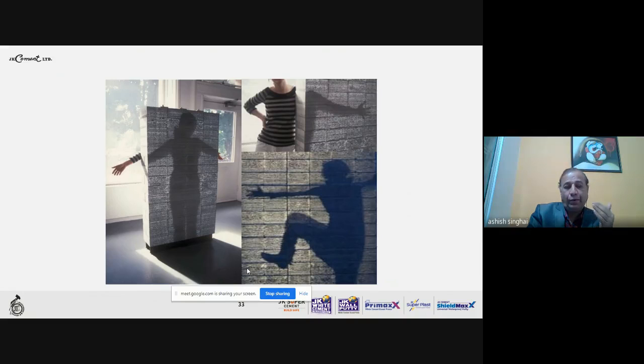So it has a good amount of water resistance. As I mentioned, the overall strength is 50 megapascal, and it has a good density because of the 90 to 95% finer materials. Coarse aggregates are almost negligible. About 4% is optical fibers, 90 to 95% is fine aggregate, and some binders and other chemicals are used to make it a composite material.